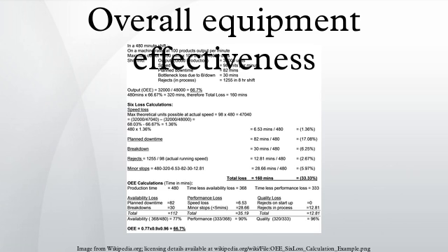It is unlikely that any manufacturing process can run at 100% OEE. Many manufacturers benchmark their industry to set a challenging target. 85% is not uncommon. OEE is calculated with the formula availability times performance times quality, using the examples given below. Availability equals 86.6%, performance equals 93%, quality equals 91.3%.